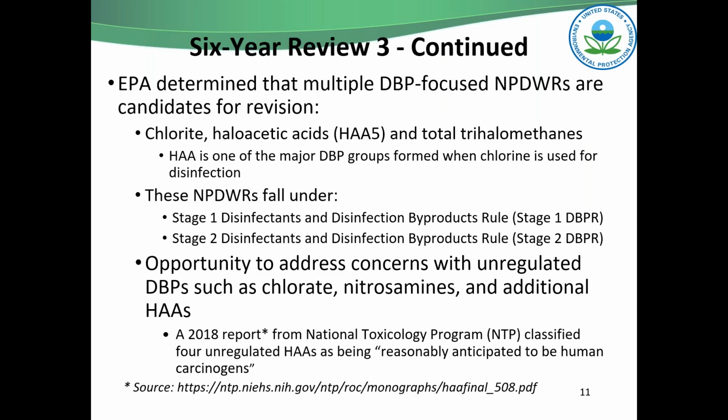For the DBPs, here we are looking at the regulated DBPs: chloroform, haloacetic acids, and total trihalomethanes. These are all candidates for revision, and they are embodied under the Stage 1 and Stage 2 disinfection byproduct regulations. There's also a report that fairly recently, in 2018, came out by the National Toxicology Program that recognizes 4 of the unregulated haloacetic acids as being reasonably anticipated to be human carcinogens.